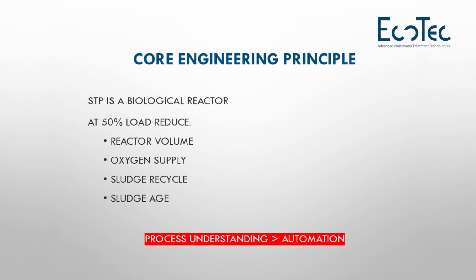One can use a DO-based operation control, but this is not a substitute for thinking. Operating a sewage treatment plant at under load needs biological understanding. We can use DO-based, VFD-based operations as a substitute for thinking, as a result of which failure becomes inevitable.